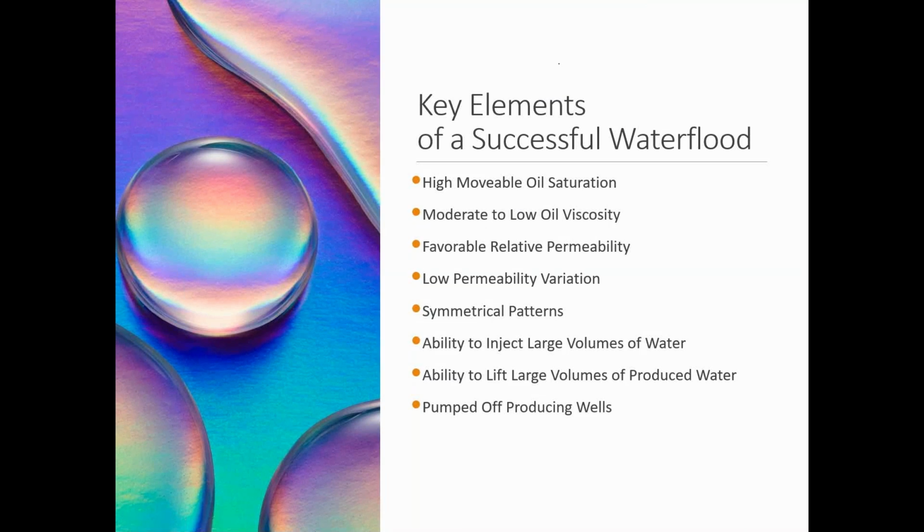If you have calculated the mobility ratio, it takes into consideration the permeability and viscosity of the displaced fluid as well as the displacing fluid. So if you are calculating mobility ratio, then you need not worry separately about the oil viscosity of the displacing and displaced fluid. Favorable relative permeability. Next is low permeability variation. Low permeability variation is nothing but the reservoir should not be very heterogeneous. If the reservoir is heterogeneous, you are injecting water at a particular point and this water is going somewhere else.